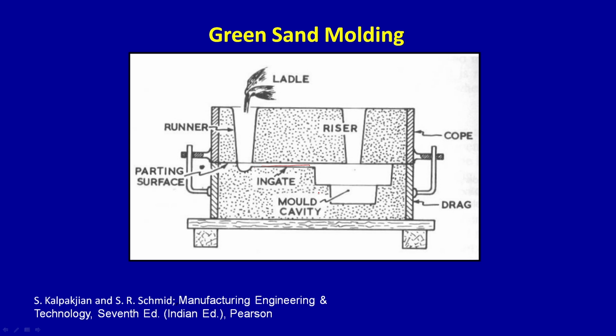But most metals shrink during solidification. So, therefore, you have to provide extra liquid, that is why you add a riser, and this riser will contain extra liquid. If it shrinks during the solidification process, the riser will provide extra metal. So, this process is very commonly used in various kinds of engineering and technologies. You have probably seen it, or many of you might have made this kind of mold and seen the solidification happening, or made a casting out of it, right.